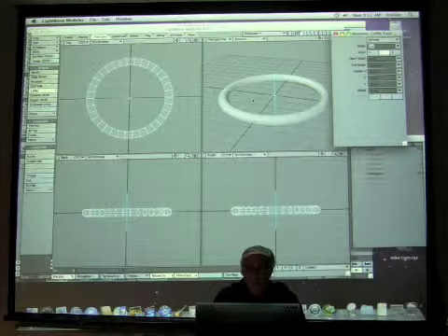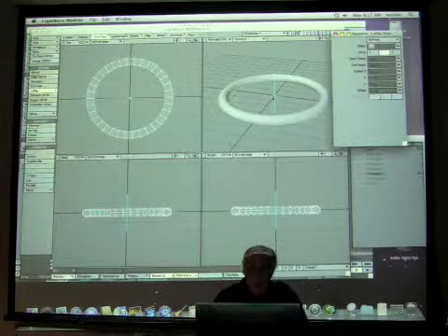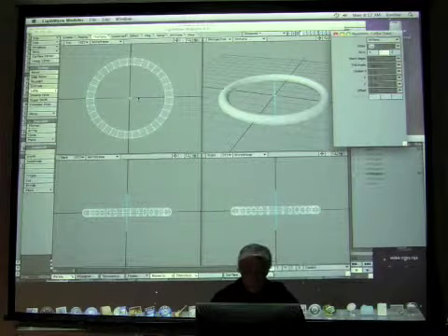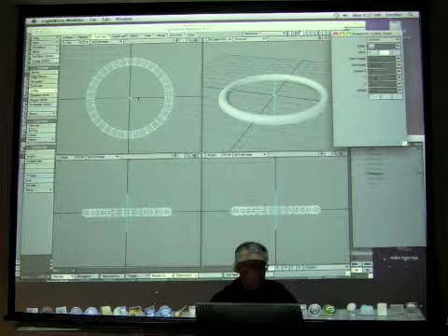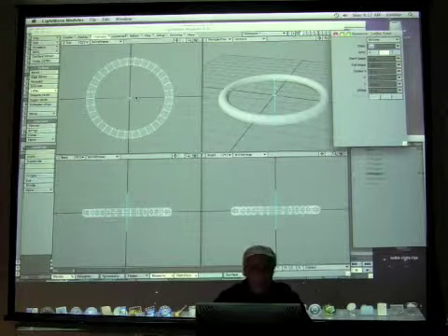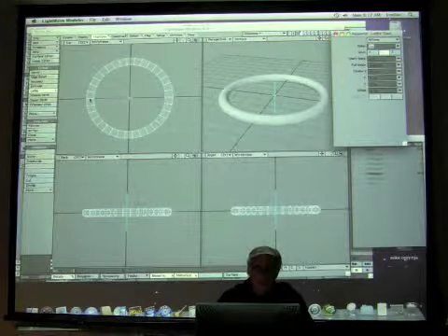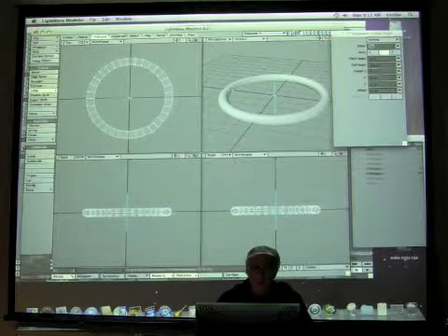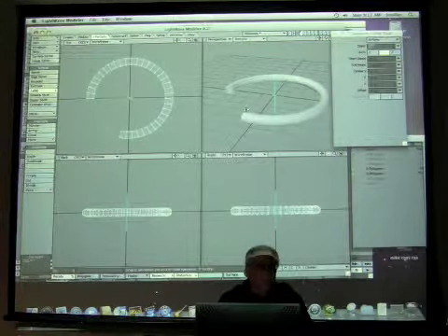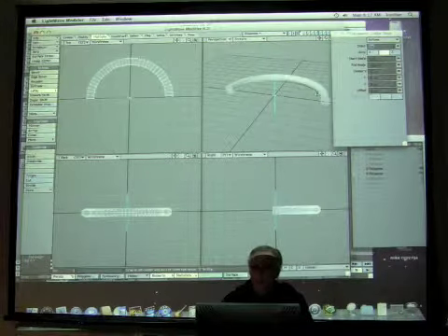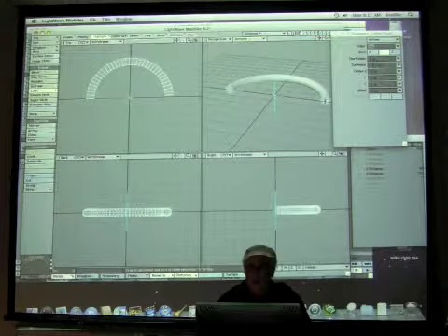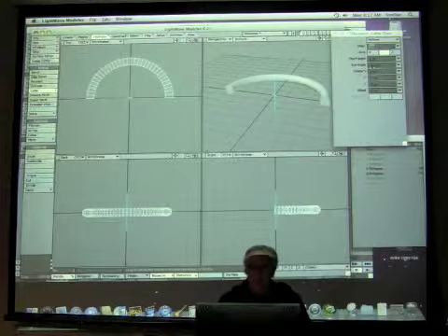And what you'll notice, look at these blue widgets. That's what I call them, these little blue tools that are similar to the weight maps we use when we right-click, or the widgets that you see when you generate a primitive. One of the things we can do is come over to the edge, and I can do this in any view, and if I only want to lathe it part way, I can. See how I'm clicking and dragging? If I look over to the right, the end angle is 177. What if I wanted exactly half a ring? Then do it 180 degrees.